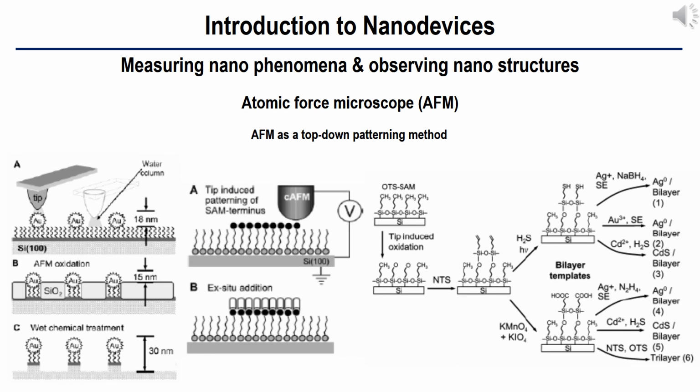The atomic force microscope can also be used for top-down lithography. Compared to E-beam lithography, AFM-based lithography has lower spatial resolution. However, it is advantageous in several aspects. First of all, the tip can be used as an electric conductor, which can apply and focus electrons on specific areas to initiate oxidation as shown in the left figure.